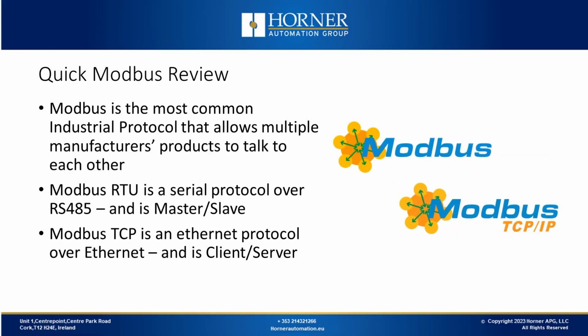Modbus is the most common industrial protocol for linking devices from various manufacturers. There are two prevalent variations. Modbus RTU is a serial protocol over RS-485 and Modbus TCP is an Ethernet protocol over Ethernet. Modbus RTU follows a master-slave configuration, while Modbus TCP is client-server.